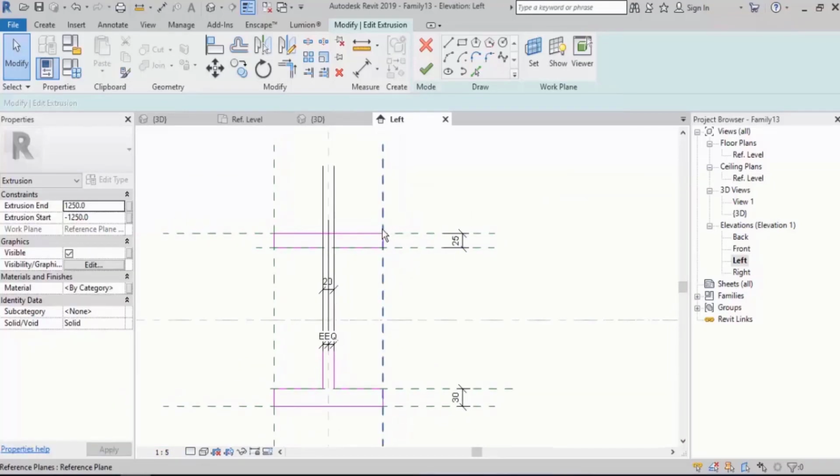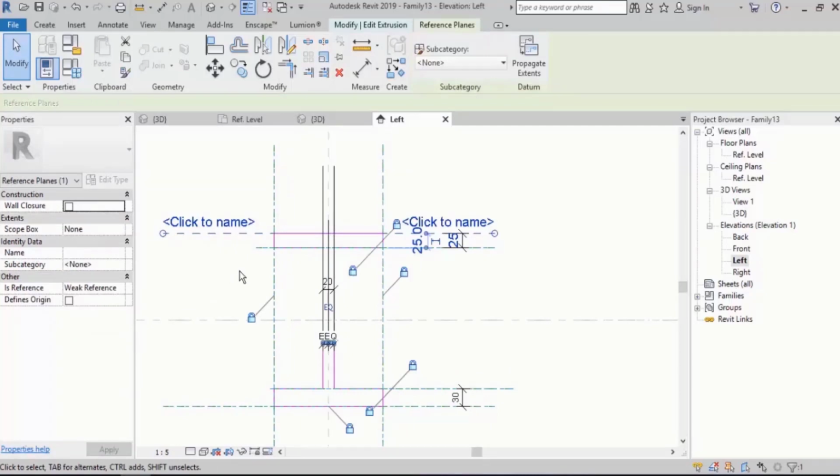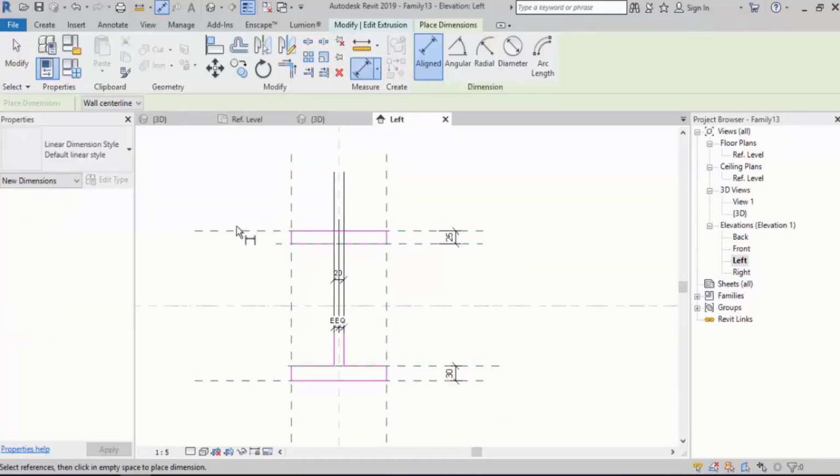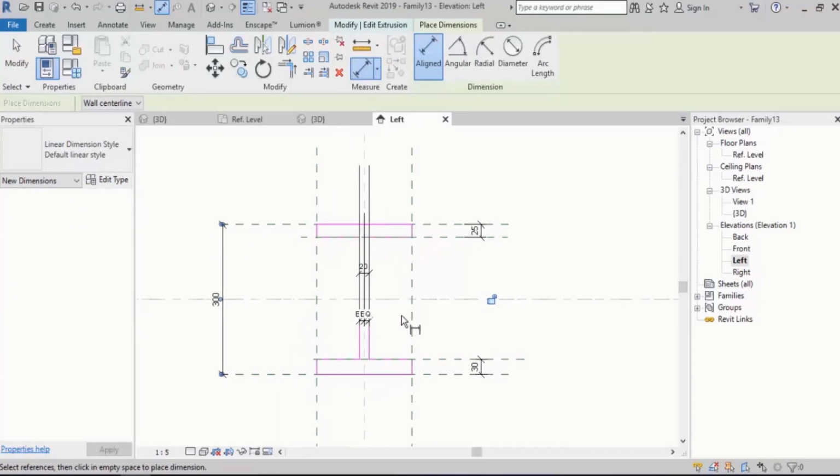Well, what's left? The width and the depth. It had a reference plane itself. If it didn't, we would draw it. So let's measure it. Does it need EQ? Definitely, because this beam should be both vertically and horizontally based on the reference plane.